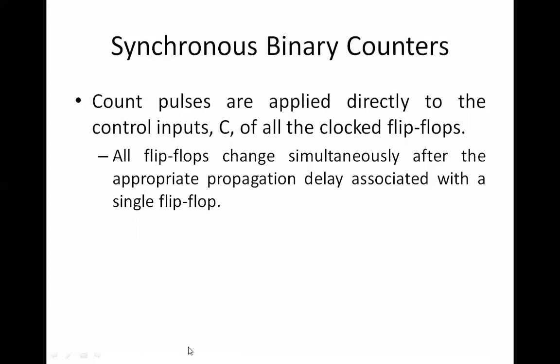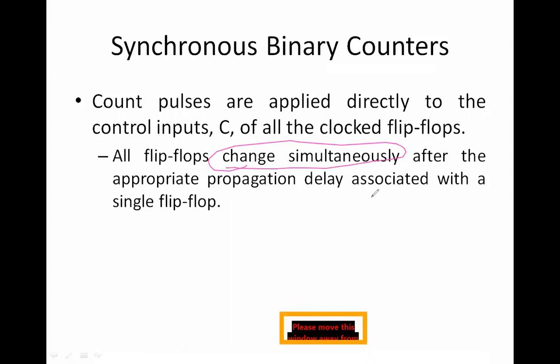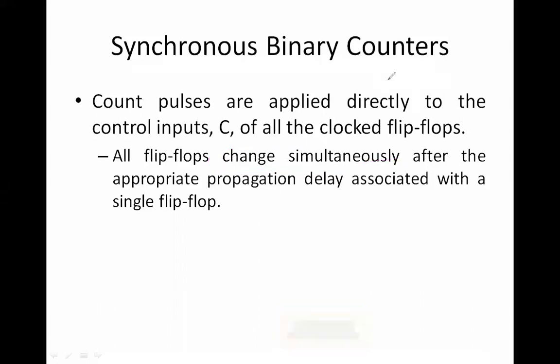Now this point is important. Change simultaneously. But then in the previous one, what was the disadvantage with our asynchronous counter? We were not able to change the state immediately, right? Because it had to wait for the value to go high, and that was delaying the output. So you can imagine it passing the values.